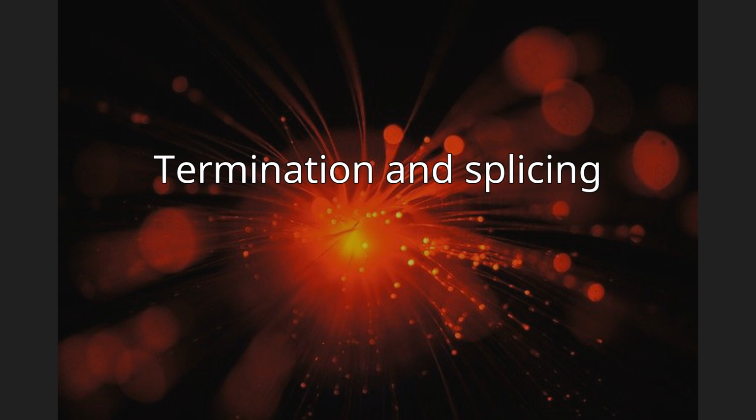Then, the splicer generates a larger spark that raises the temperature above the melting point of the glass, fusing the ends together permanently. The location and energy of the spark is carefully controlled so that the molten core and cladding do not mix, and this minimizes optical loss. A splice loss estimate is measured by the splicer by directing light through the cladding on one side and measuring the light leaking from the cladding on the other side. A splice loss under 0.1 dB is typical.